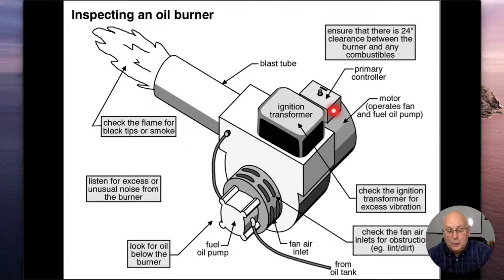The primary controller, all right, the purpose of that is kind of like a reset button. And so basically our thermostat calls for heat, our pump, our motor kicks on, we start spraying oil into the unit, we're blowing oxygen in there, our igniter is sparking, and we should start a fire. If we don't sense the fire, then the unit's going to shut itself down. The only way it's going to restart again is to go press this primary controller button and get it to restart again. All right.